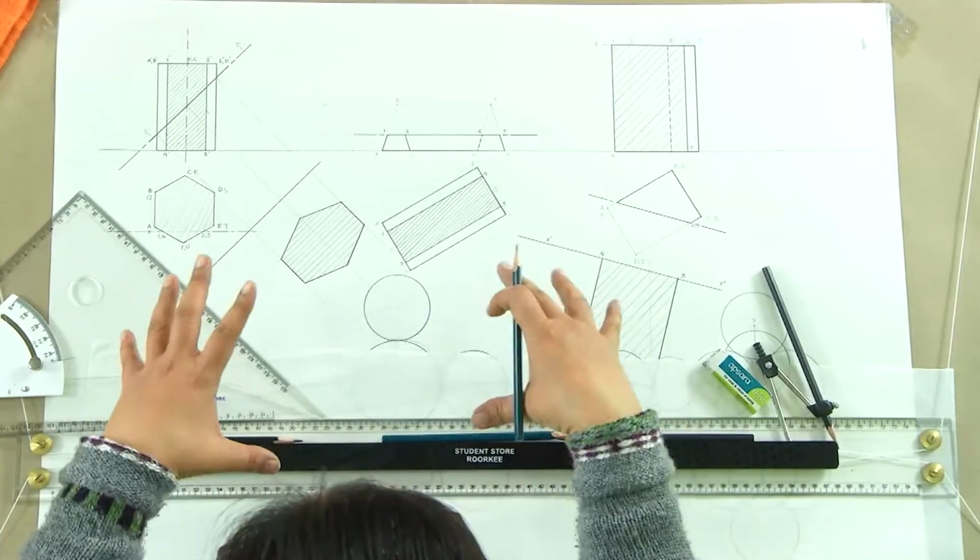So with this I have explained to you the 4 cases of how prisms can be cut by a plane: perpendicular to HP and parallel to VP, parallel to HP and perpendicular to VP, inclined to VP and perpendicular to HP, and inclined to HP and perpendicular to VP. In these 4 different given conditions, we have seen how to draw the sections of the prisms.